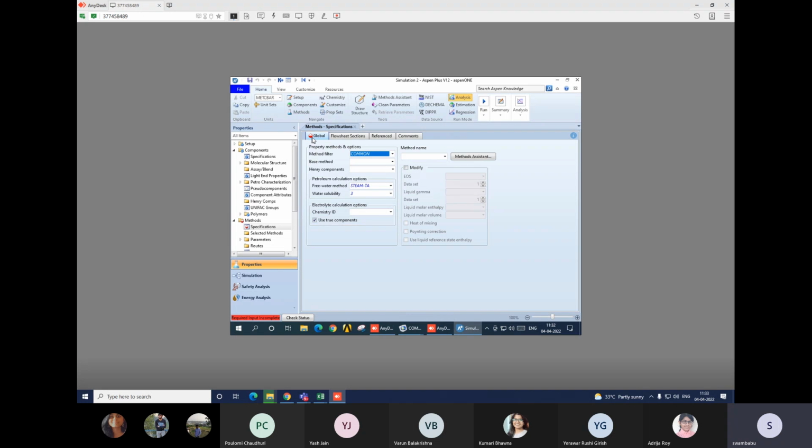If you see a half-filled circle with red color, that means we haven't specified the required things. The same conventions are used in DWSIM. If whatever stream you have selected is in red color, that means we missed something in the definition part. Once it turns blue, that means whatever is needed we have defined.